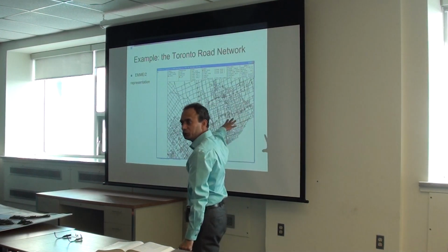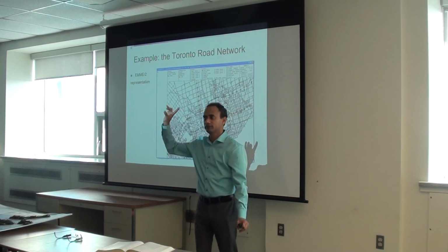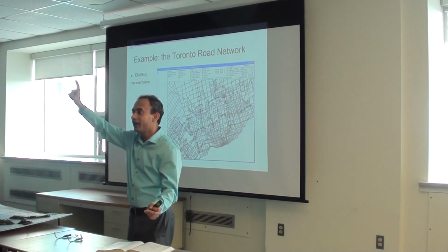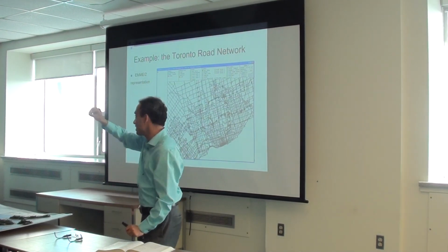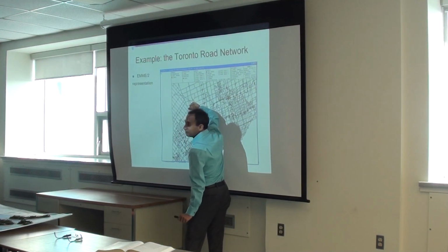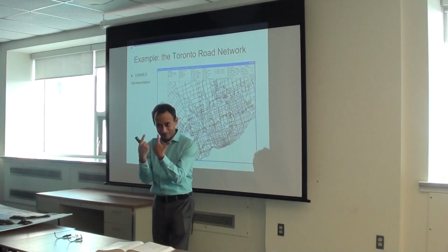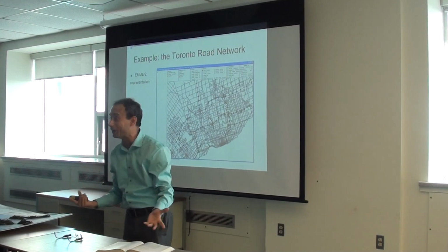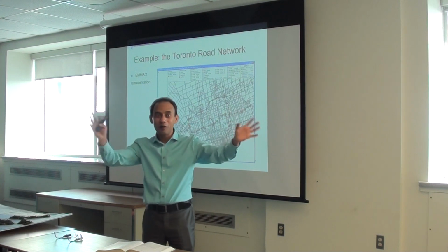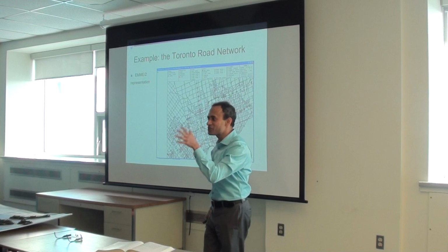So what we first need to do to abstract is create the street network. That's number one. Street network, which is nodes and edges, right? Nodes are our intersections. See, this is our intersection and the link. And why two lines? Two-way, so that we can flow people two-way. It's a flow model. If anyone is from civil engineering, water flow modeling is a similar kind of thing. For us, it's easier because it's a straight line.